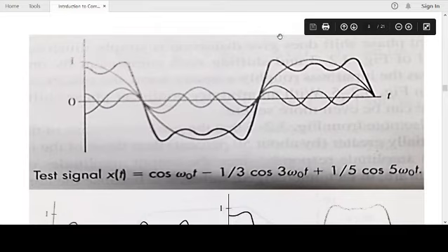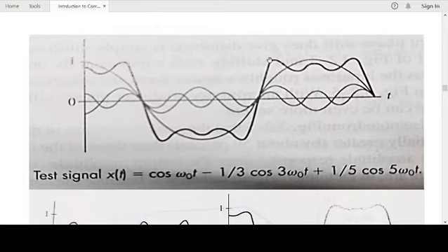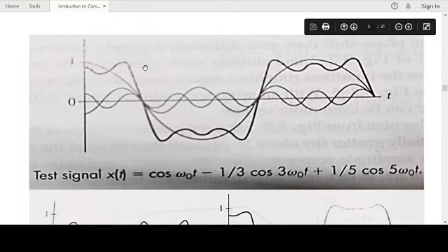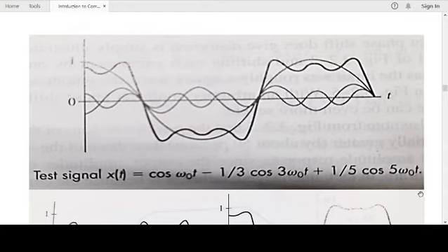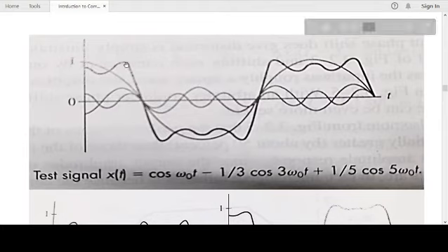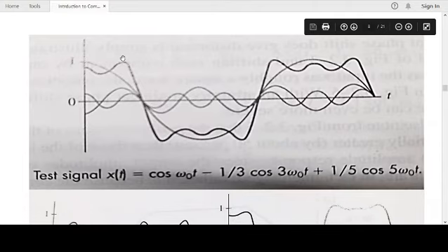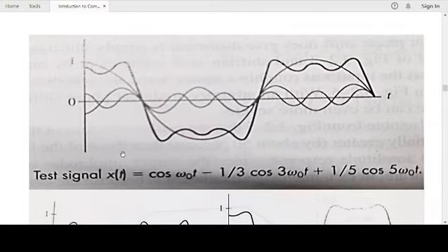And so, because the square wave at the junction, at this transition, is a non-differentiable function, and you are approximating it by a continuous, differentiable, nice smooth function, naturally the combination of all these harmonics would not ideally give a square wave, right? A combination of differentiable functions won't give you a non-differentiable function at certain points, and hence those artifacts come into the picture. Okay, so you have probably studied this in signals and systems. You may please revisit Oppenheim and Willsky's book to take a look at Gibbs phenomenon.